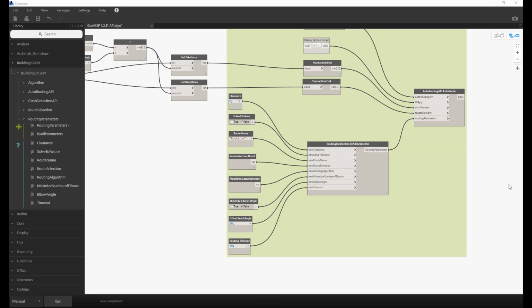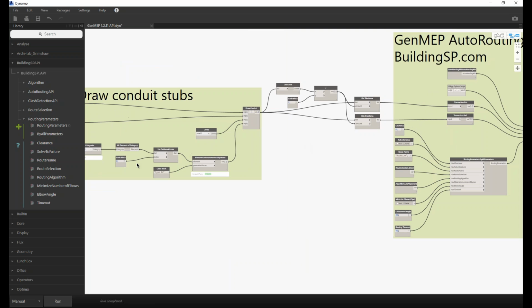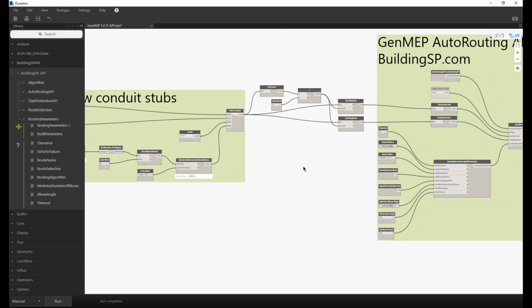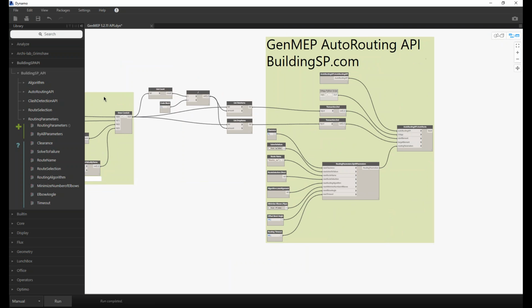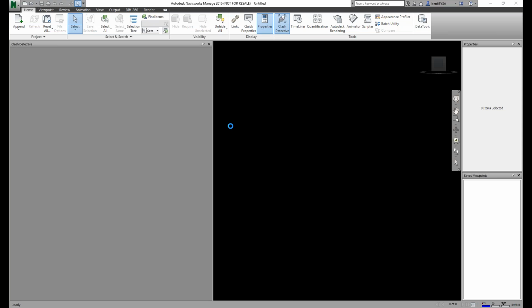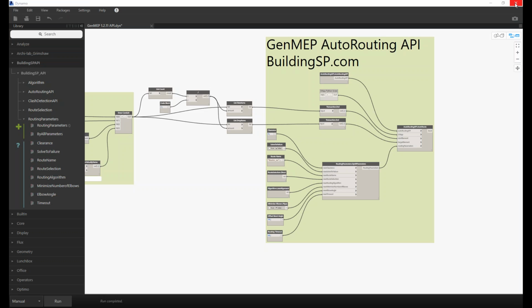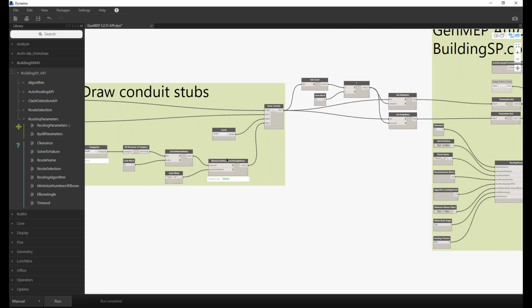The first thing that we have is an automated hanger tool. What it does is, if you define a point in a Revit model and pass a parameter that defines a cylinder diameter, we will check whether or not there's anything within that cylinder vertically going up.